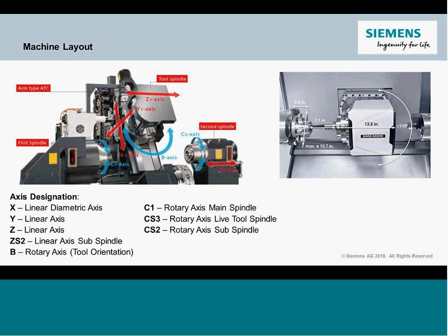Is it S1? Is it C1? Is it some other number? Some just like to always use the same terminology for spindle locations, and then if your machine just doesn't have that type of spindle, like a secondary turret, let's say, then they just skip over that one. So that's a pretty common method too. When looking at the B-axis, it's important to start to get your head around where this B0 is, where everything drives from. So if you look at the image on the right side, this is a very, very typical configuration of a setup for a B-axis lathe.